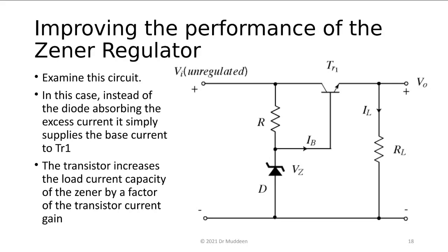So that's why, when I was doing the calculations and the Zener current came up to 0.25, for safety you said to do a half watt. Absolutely. We mentioned that yesterday with the transformer as well, and the capacitor as well, that you always give a safety margin.